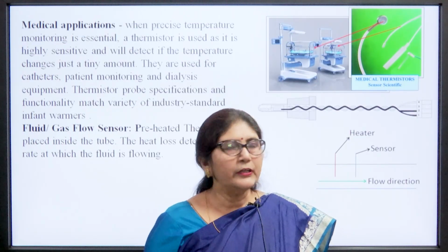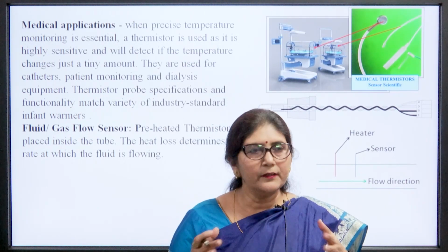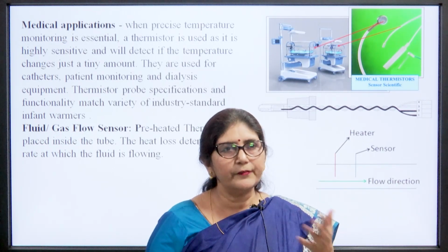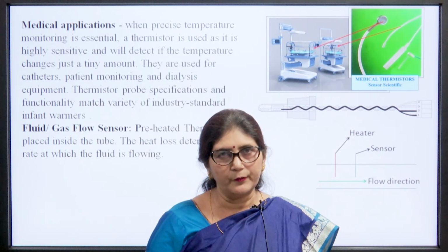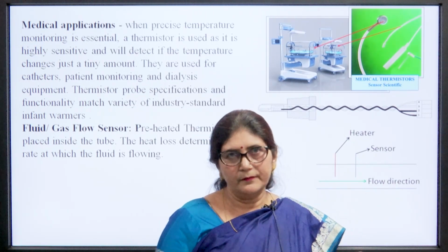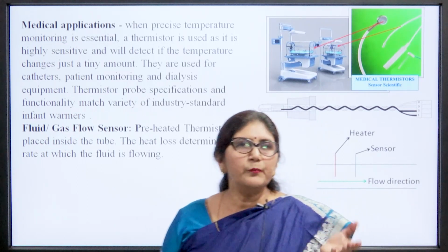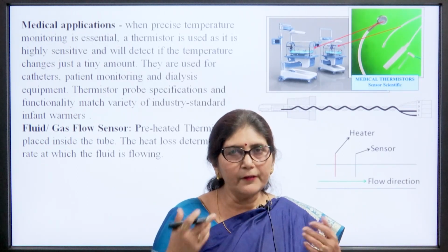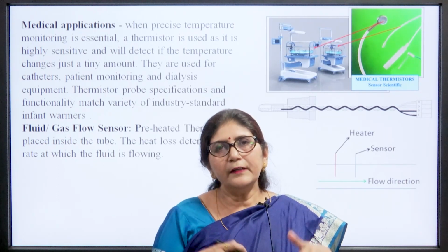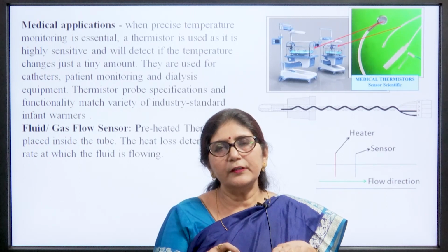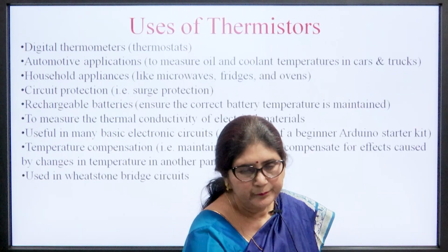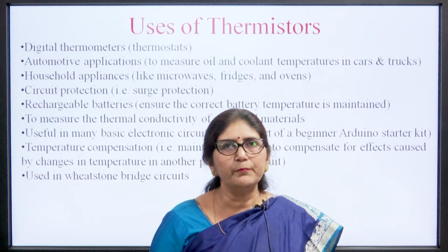In medical, in incubator centers where newly born babies are kept, thermistors are used because they are very sensitive and have a very fast changing response. Similarly, it is also used in fluid and gas flow places. One property of the thermistor is that when it is self-heated and water or anything is flowing over it, there is a change in temperature, and that change in temperature indicates the change in flow.